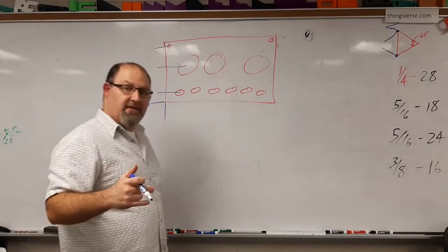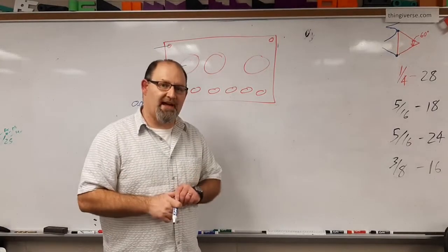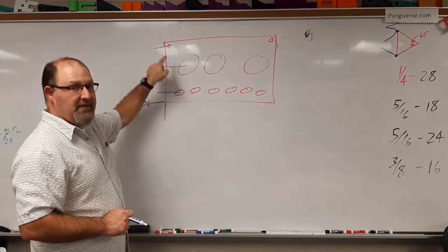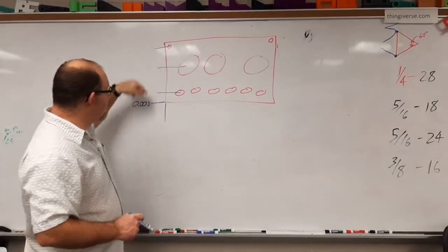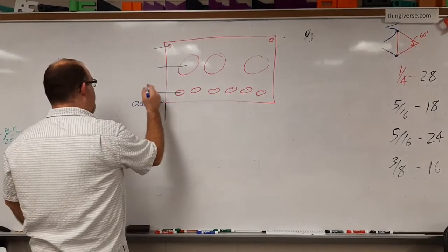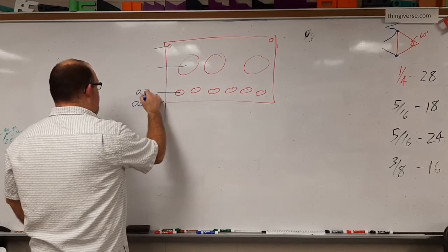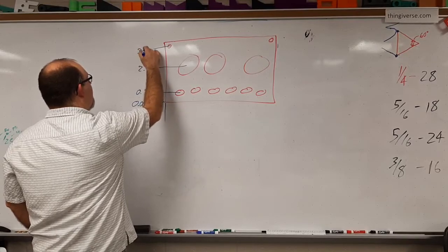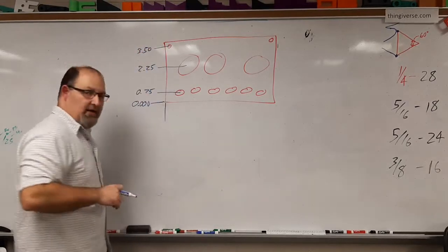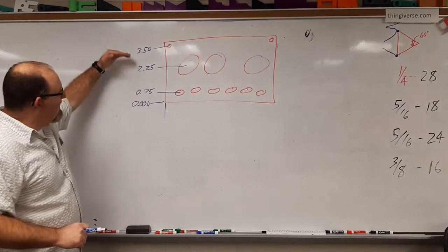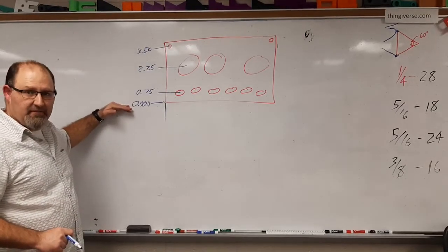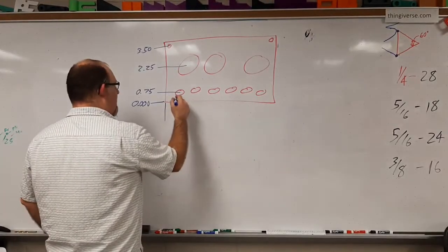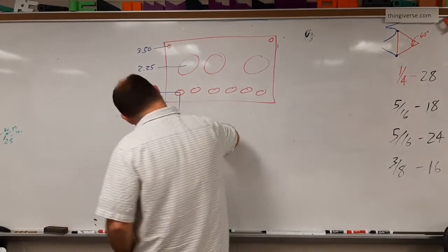By the way, in AutoCAD there is a function where you can dimension with datum dimensioning. And when you do, you establish the datum, you just pop in these points, and it automatically builds this in with the numbers. So here, let's say that it's 0.75, 2.25, 3.5, and so on. Okay? What these numbers are, they're a reference to this datum point right here. Same for this edge. This edge here being a datum point of 0.00.